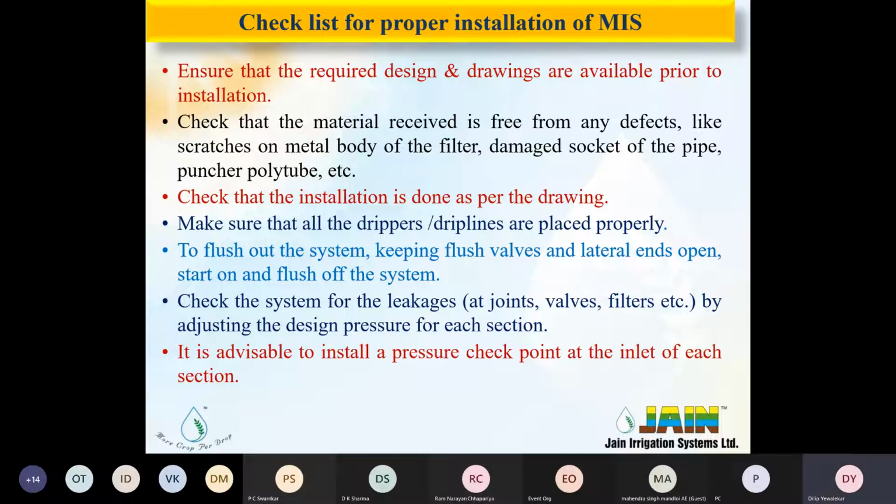Then after that, the drip line shall be placed properly, flush out the system, then check the system for leakages anywhere in the joints and filtration system. If there are any leakages, just fix them. These are simple tips before installation.